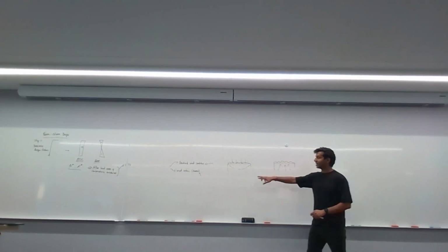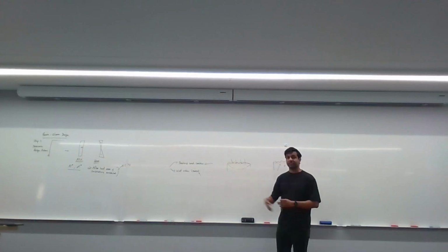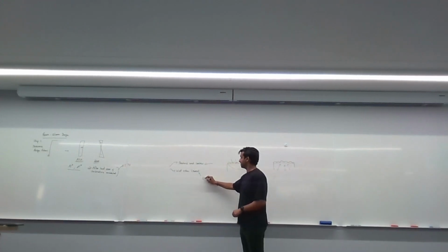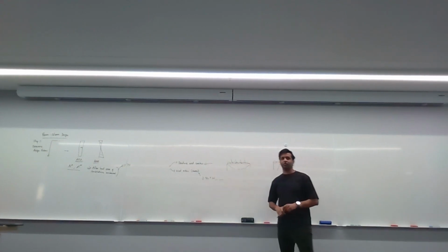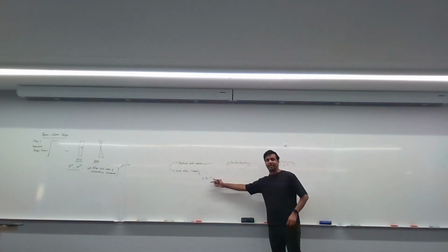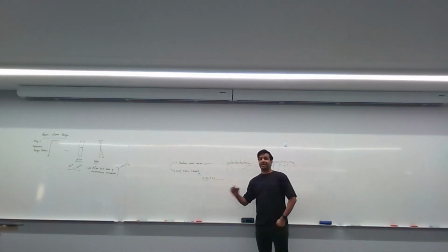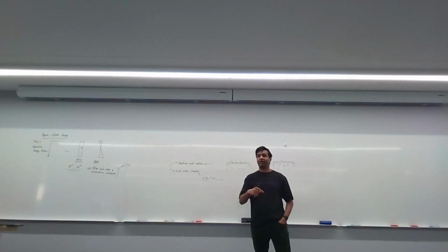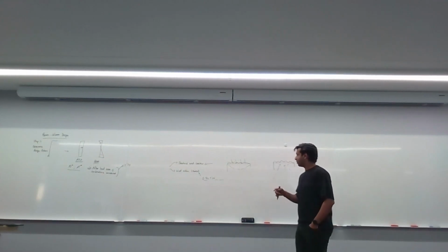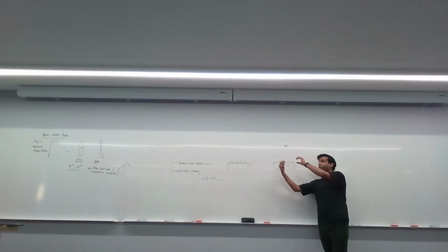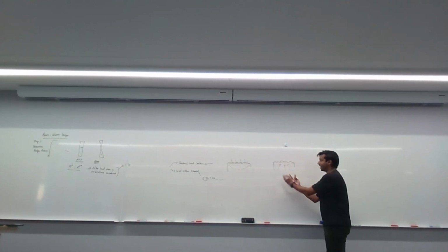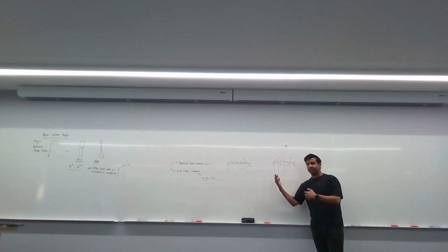What the wind action reversal load combination does is it does 0.9G plus W, and I believe it's something like that, or there might be something else. Have a look at the code to confirm. But basically, that's what it looks like. You have G, your factor for G is less than 1, it's 0.9. Okay? So what they're trying to do is they're trying to not aggravate the dead load component, right? Because the total action of this wind blowing up is actually upwards. Okay? So you have to consider that as well.